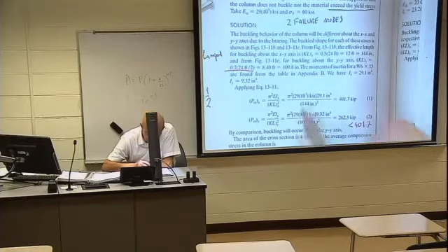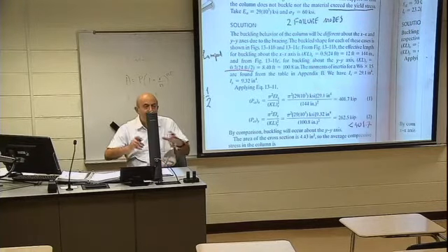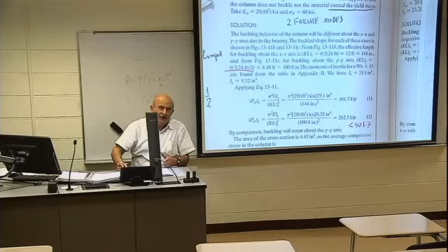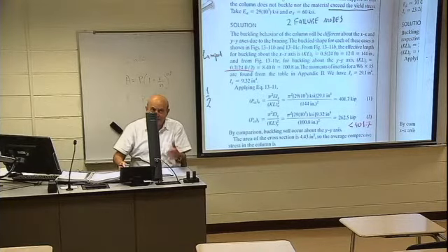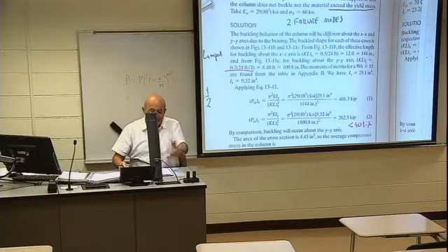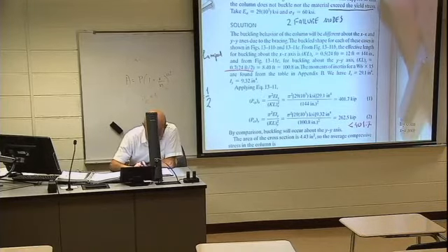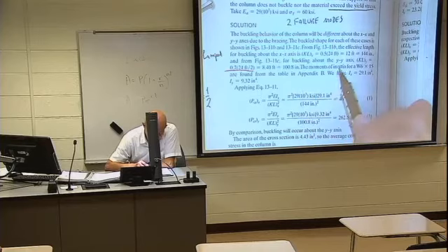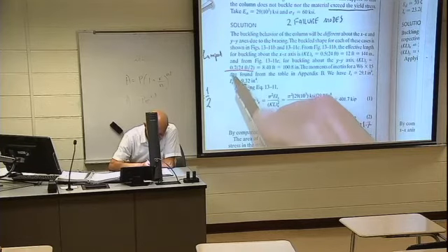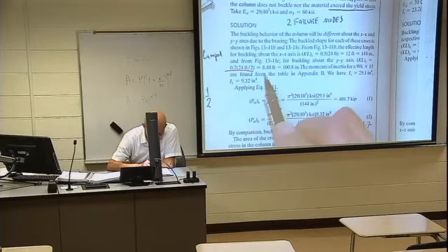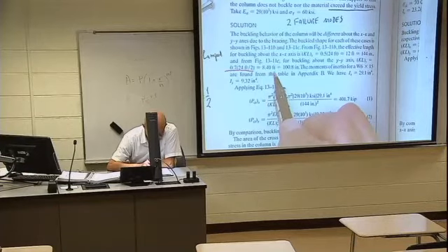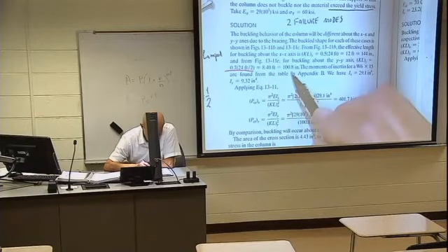Okay? Please repeat this KL business. I am not starting a lecture with absolutely new material. I am relying on previous material. In order to understand this material, we have to know the previous material that was covered in the previous lecture. And I cannot repeat this material again and again. So, about the y-axis, KLY equals 0.7 of 24 feet, okay? And that equals 16.8 feet, or times 12 equals 201.6 inches.